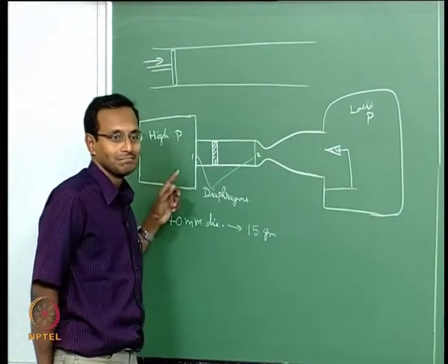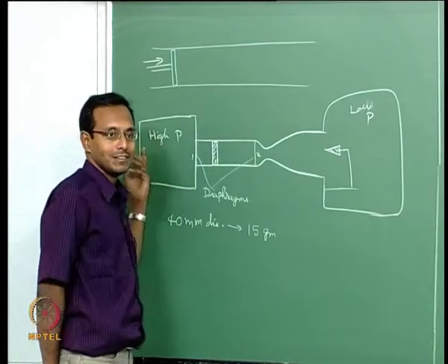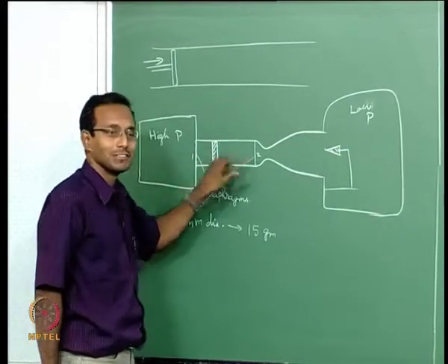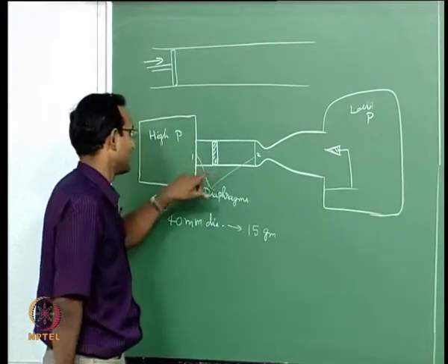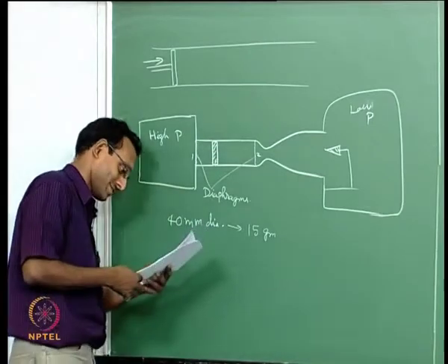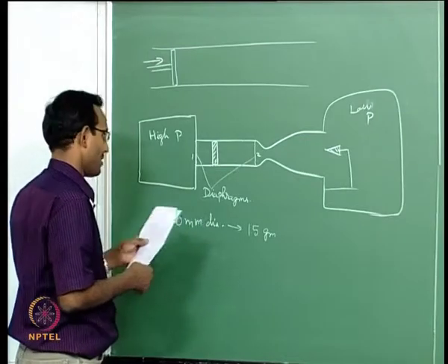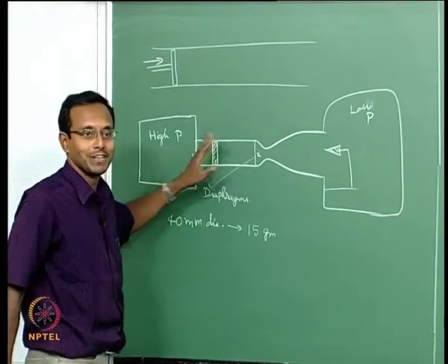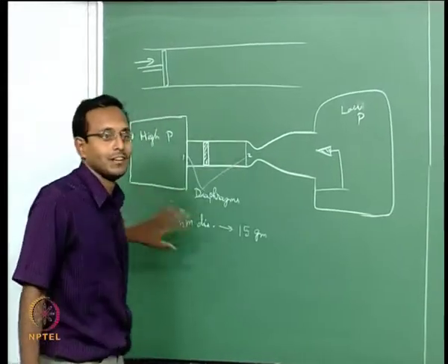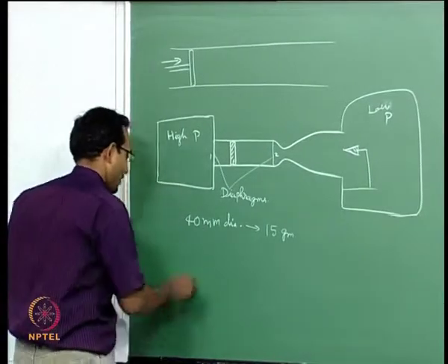A reflected shock tunnel is not that capable of doing this, because if I am reflecting just once, the pressure jump and temperature jump may not be very high. That is one better thing about this tunnel. And the second thing is I can use some special gas and I do not need to store it in really high volumes. And if you think about it, after the diaphragm breaks, it is exactly the same operation as your reflected shock tunnel, nothing new.